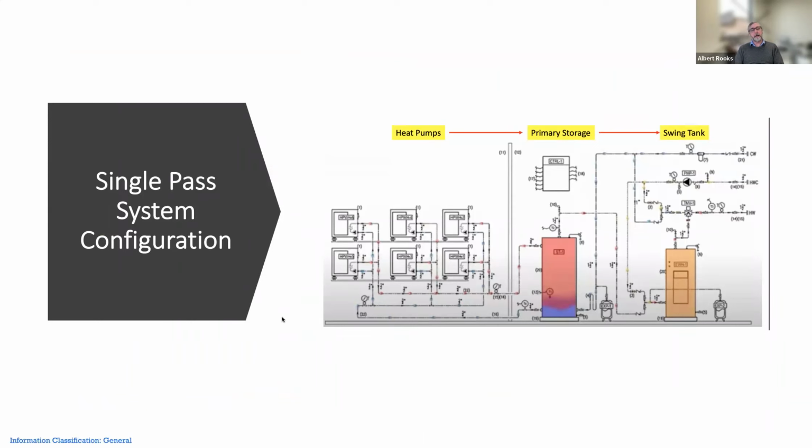So now we're going to talk about how these things work. And the relationship is really heat pumps, one big one or a collection of small ones. In really big buildings, we could have a collection of really big heat pumps all working in series, producing high temperature domestic hot water and sending it into that second cell, the primary storage.